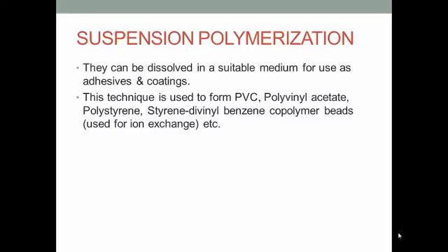Suspension polymerization is most commonly used as an industrial manufacturing method to get polymers for forming materials such as polystyrene, polymethyl methacrylate, polyvinyl acetate and polyvinyl chloride, because a polymer with a high degree of polymerization is obtained, and isolating the generated polymer is easy.